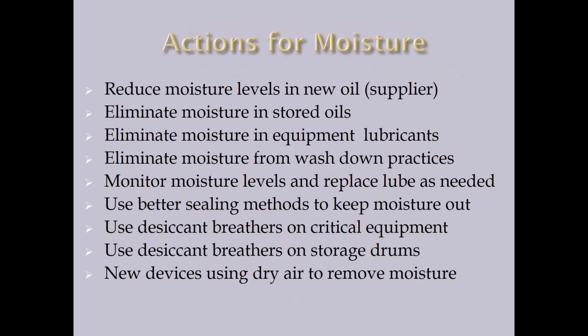But again, we have to have some actions for this moisture. What about the moisture level that comes in from your new oil supplier? Many times we don't check that. So one of the things I always tell people is go to your oil supplier, who you're buying your drums from. Find out how they're storing your drums.